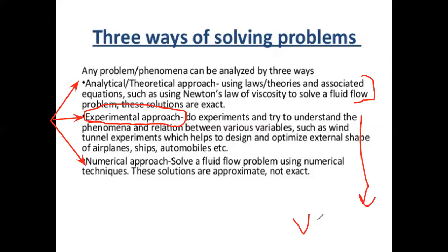What do we mean by this? When you develop a CFD model, sometimes you need to do some tuning. You need to alter some coefficients, you need to update some models in a way to give you results very close to the real case. So when we develop a model, we should test several meshes until reaching a convergent solution. And even the convergent solution can be enhanced, so I can use a finer mesh size to give better results.